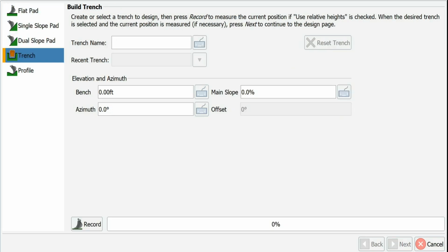Trench is a tool for creating cross-section templates for underground utilities. Along with giving you a target cut or fill to invert, you can create multiple node cross-sections. This would be useful for utilities that need to be buried deep, and you can create benches in the trench to keep the guys in the trench safe.